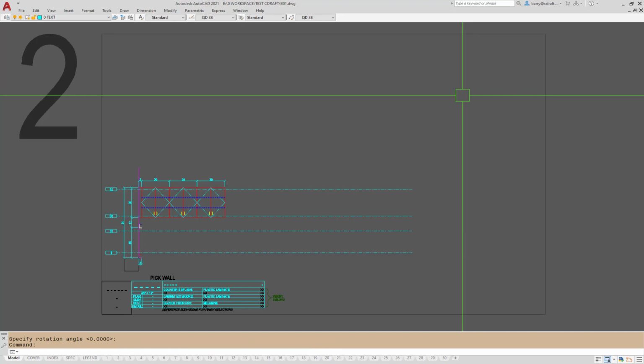Now, let's add a 1 drawer, 2 door base cabinet. So that's going to be a B12. B for base cabinet, 1 for 1 drawer, and 2 for 2 doors. Spacebar, and our first option is going to be the width.